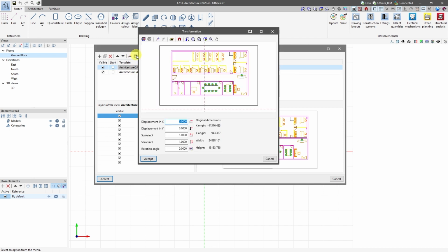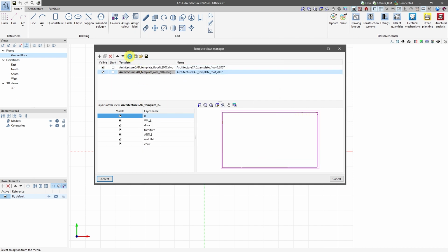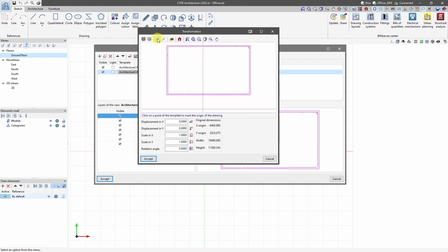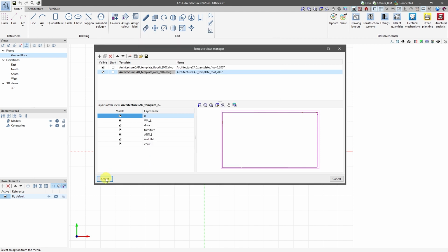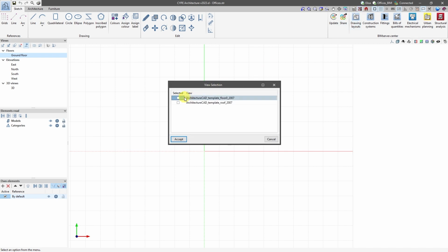We then check the coordinate origin and the scale thereon. We make corrections if necessary. The origin is marked by dotted lines. In this case, we place it in the upper left corner of both. The lines don't appear yet because they must be assigned to each view.